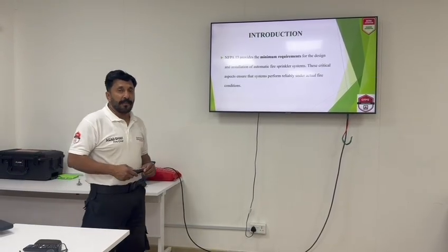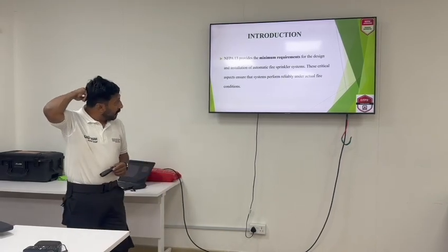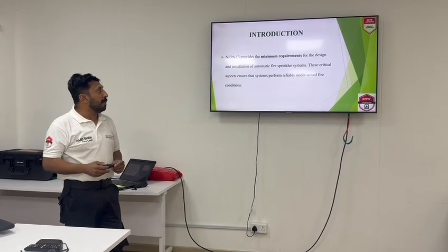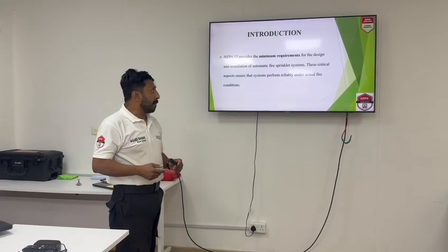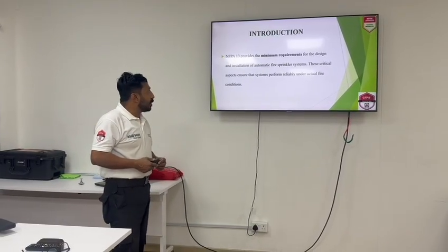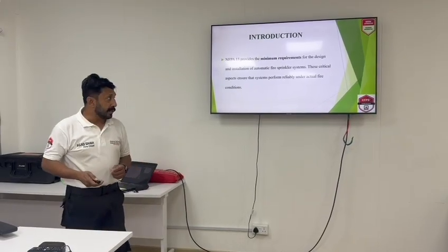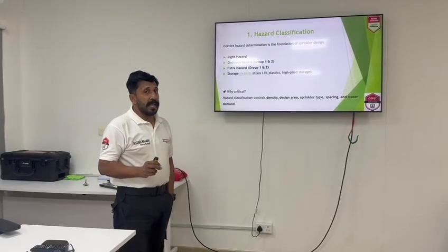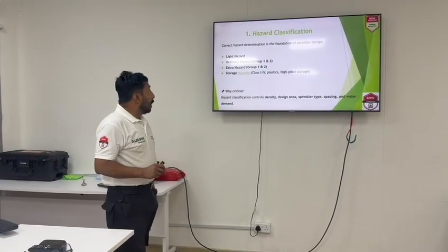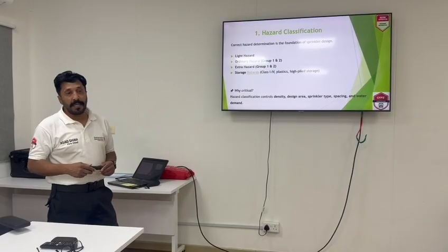The first thing we should know is what NFPA 13 is. NFPA 13 provides us the minimum requirements for the design and installation of automatic sprinkler systems. These critical aspects ensure that the system performs reliably under actual fire conditions. So the first point is hazard classification. Correct hazard determination is the foundation of sprinkler design.